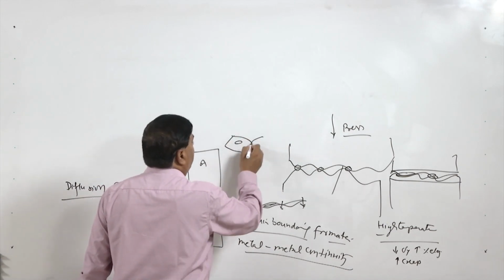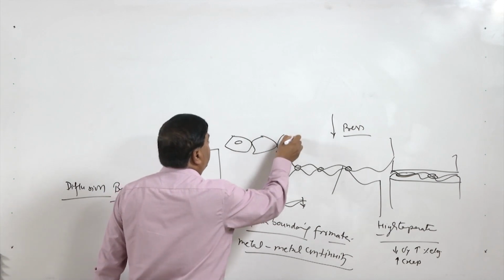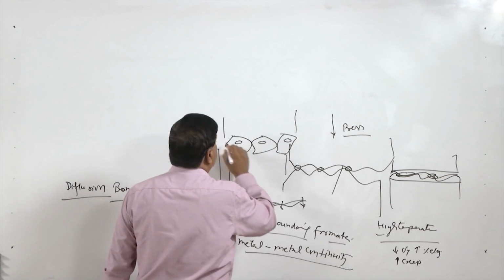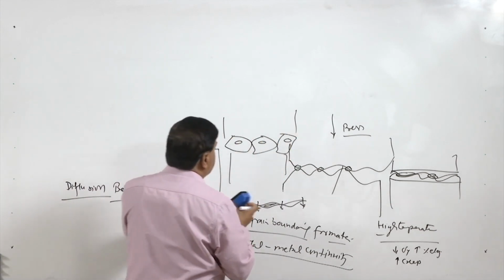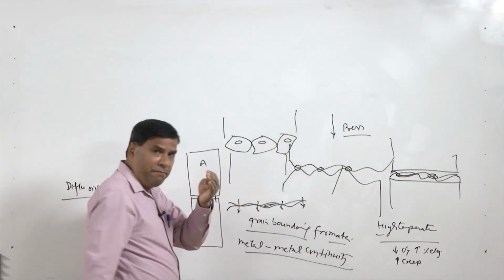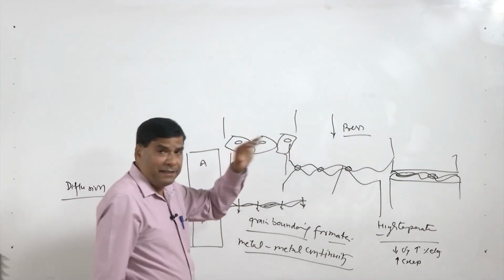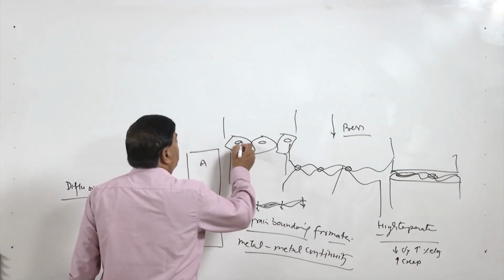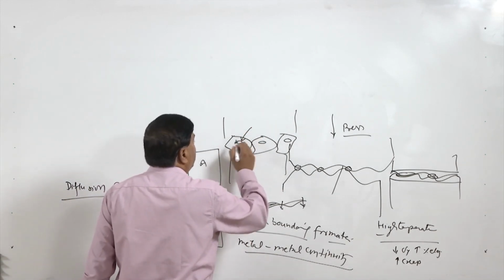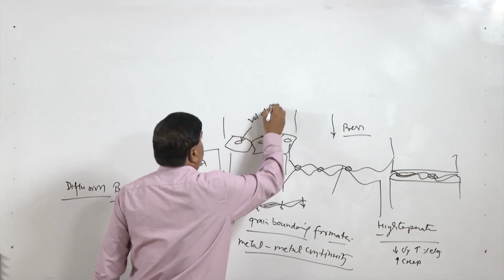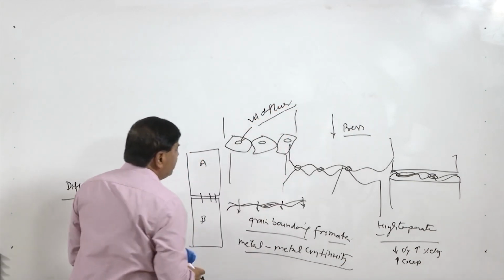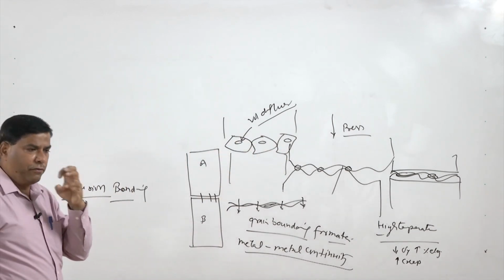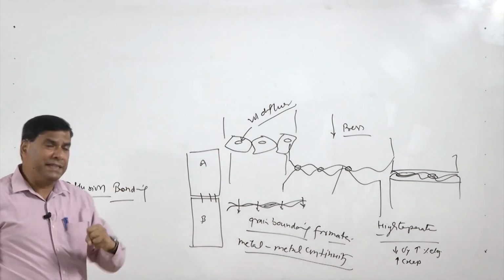material grains have been formed all along the interface, and the pores are left in between like this. So, the grain boundaries across the interface have been formed, but the pores or the unbonded areas are left within the grain. So, in the third stage or fourth stage, the volume diffusion facilitates the removal or elimination of these voids and the porosities left within the grain.